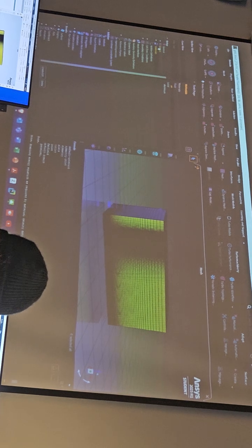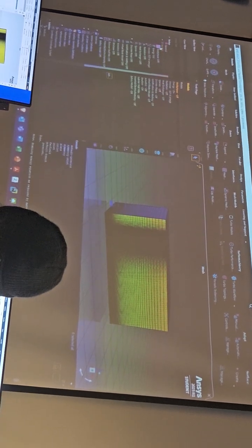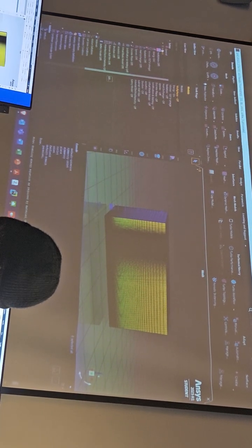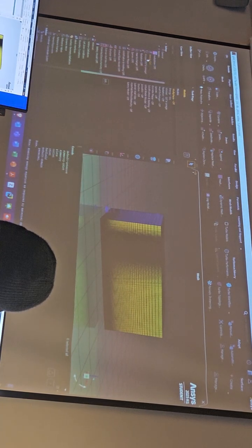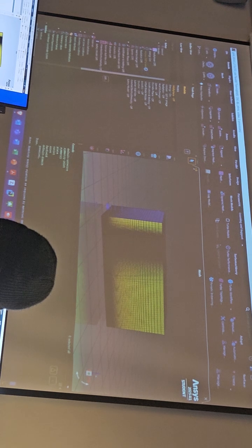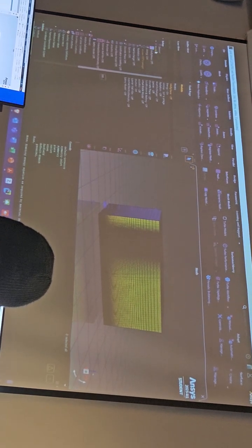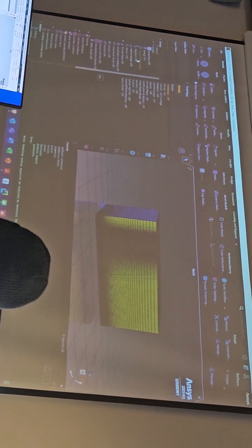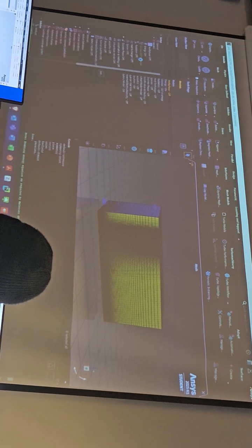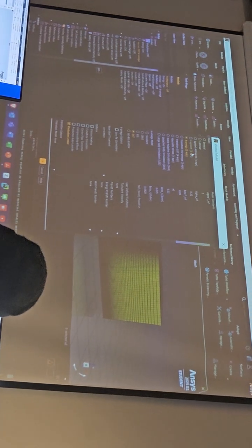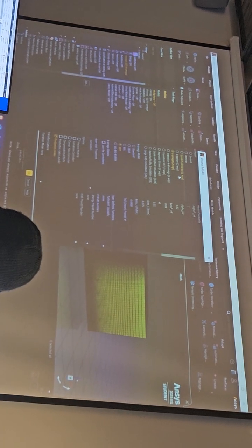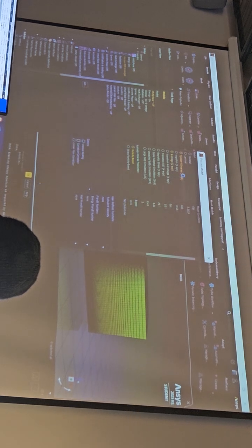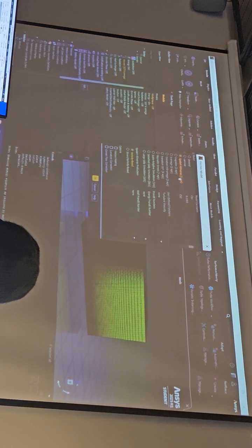Next, now we go to the turbulence models. We need to set the viscous model. So in models, now the energy is on because this is an ideal gas, so it needs the temperature calculation. And in viscous, now we have the SST k-omega by default. And we were asked to simulate this case with a one equation model. And we have this Spalart-Allmaras one equation model here. So we can select that.